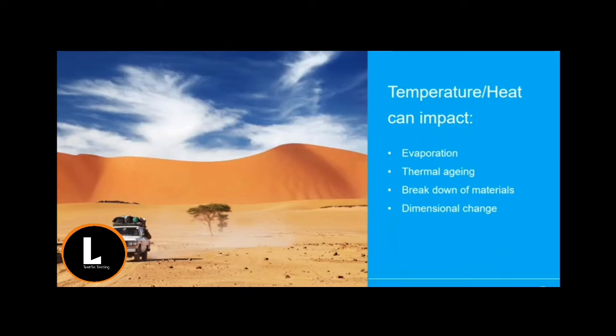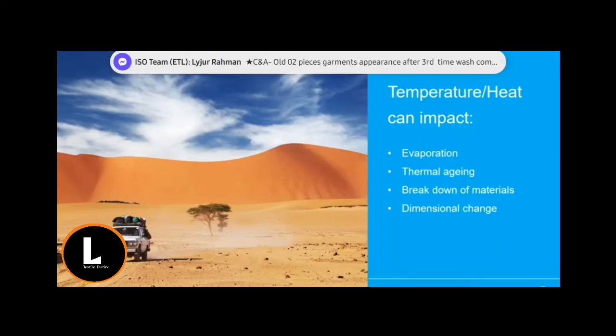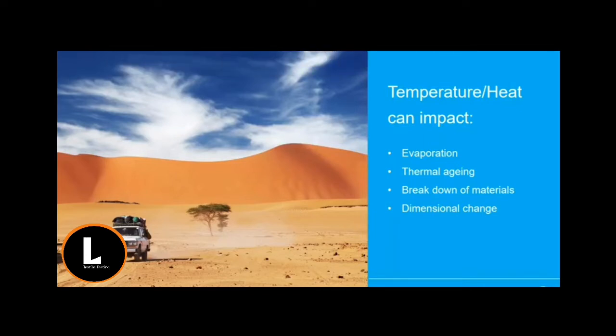The colour of the specimen can also affect how hot the fabric will get, as black absorbs heat and white reflects it. And this is why the thermometer in the xenon arc tester is black. It's black to absorb the maximum amount of heat to record the highest reading that a specimen will be subjected to.